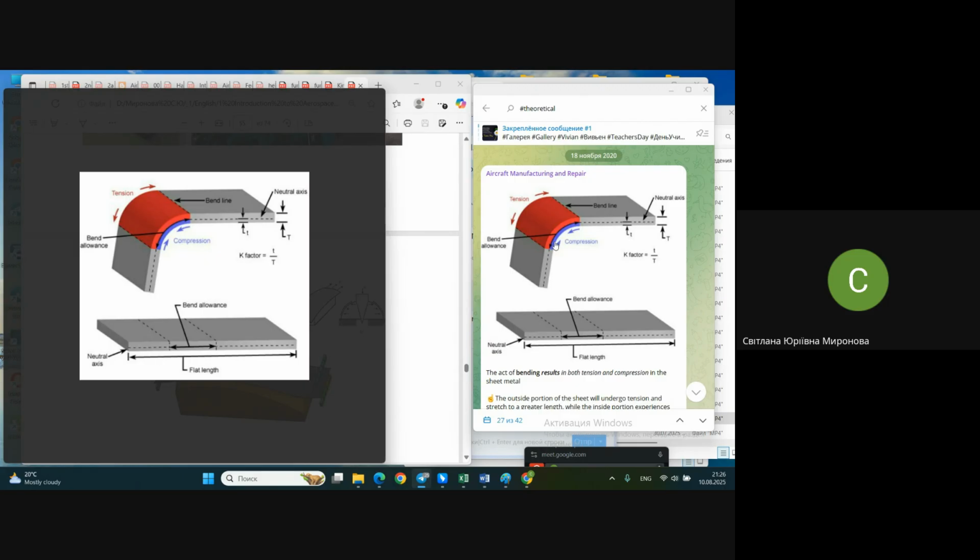Their sizes are great and their shapes are practically flat, barely deformed. In this case, this spring back effect will be very unpleasant. And the parts are great in size. What does it mean for us? A great size part means a huge punch, a huge die block, and huge equipment to operate with.